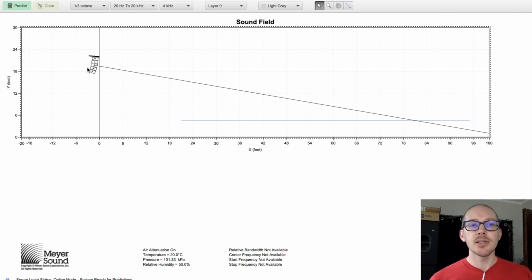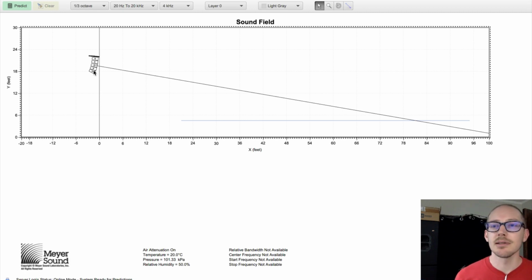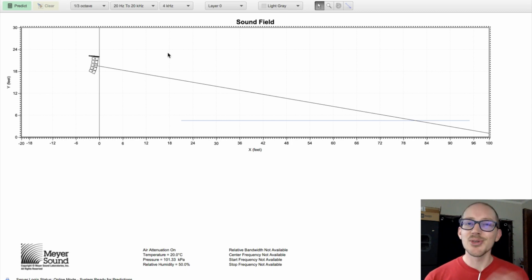Try turning down these bottom 2 boxes. If you turn them down 6 dB and you don't see any of the traces move, then forget about it. You're not going to have any success. But if turning down these bottom boxes does, in the high end, bring everything together a little bit more, and maybe you walk around and you like how it sounds, then that can work for you. Again, with these smaller arrays, I've found that it is often unsuccessful to do any level changes of the boxes. But I do always like to give it a shot.